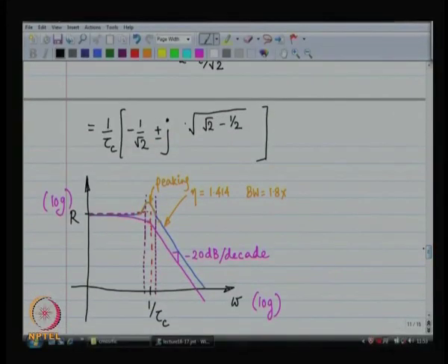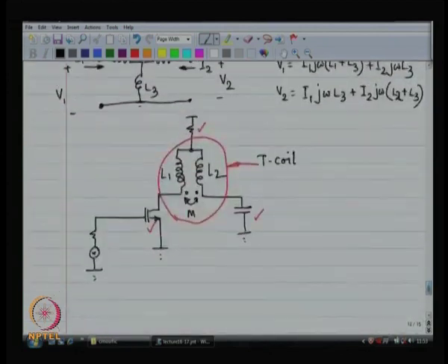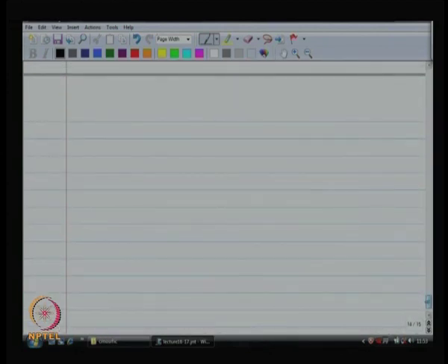I am going to discuss one more, which is using the principle of feedback. So far what have we seen? We have seen that instead of having a regular RC circuit, we can introduce some poles and zeros, a pair of complex conjugate poles and a zero, right, and we can try improving the bandwidth. Over here, as you progress towards the T coil, you include more and more poles and zeros. I mean, these are more complicated systems, the order is much more. All right. So, you basically go to higher order.